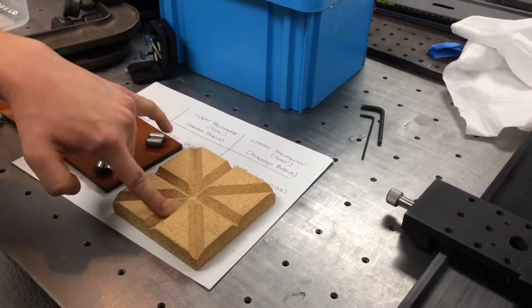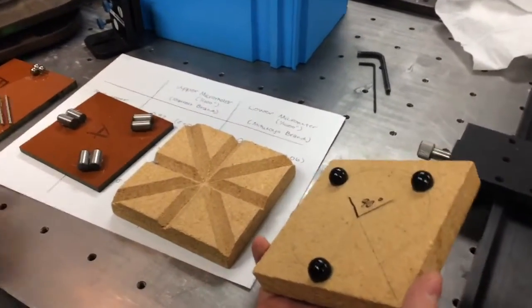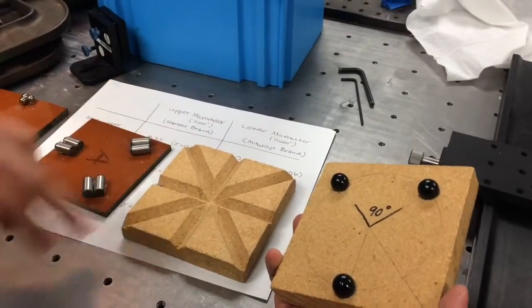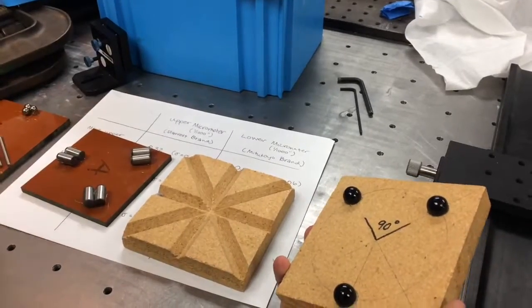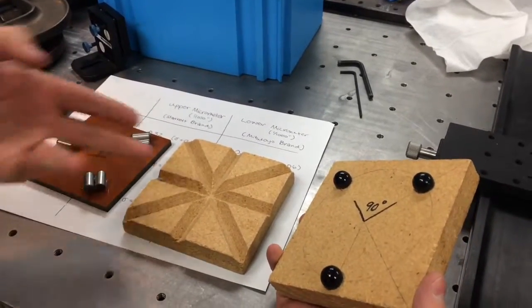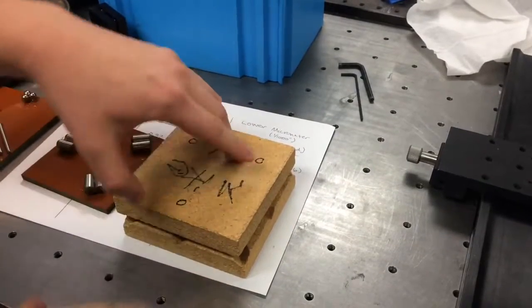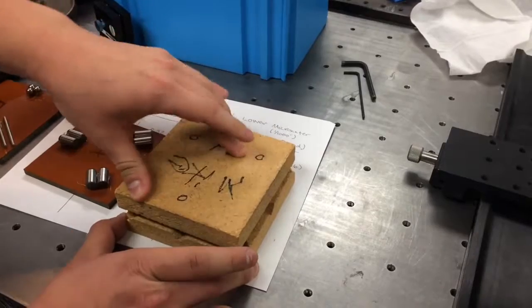I'm talking about the grooves here, here, and here in this case. Each sphere has 2 points of contact due to the groove. That means that in total there are 6 points of contact, and this just so happens to be a kinematically constrained system because it constrains all 6 degrees of freedom, and this top plate no longer moves.